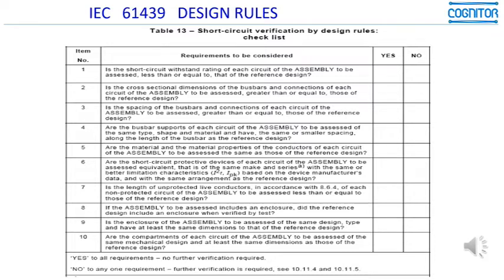The third rule: is the spacing of the bus bars and connections of each circuit of the assembly to be assessed greater than or equal to those of the reference design?